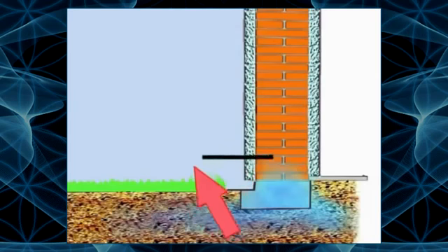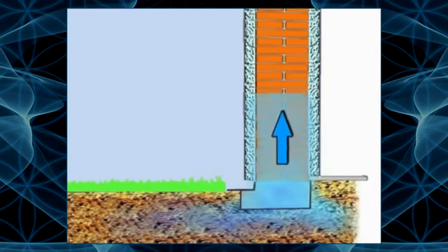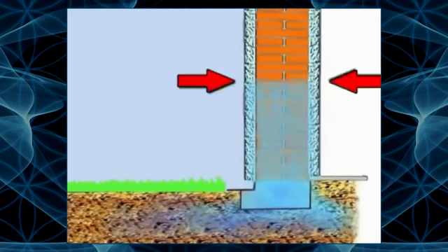In old masonry that lacks a horizontal moisture barrier, or where it is partly rotten, ground moisture rises into the masonry. Ground moisture in the capillaries of masonry rises to a point where it oozes out as water vapor at the so-called evaporation zone. This results in the capillary head in masonry, which grows a little every year.